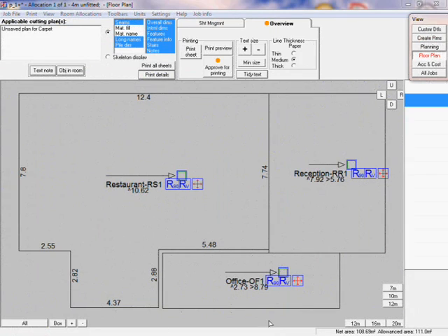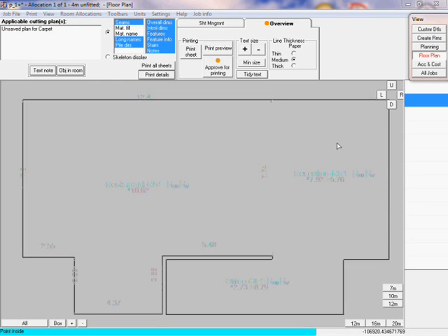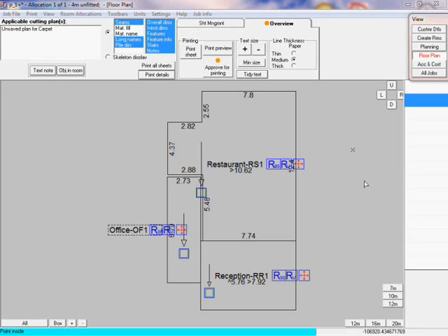We will now go to the floor plan and see here that it shows the architect's view of the property as represented by the outlines drawn. We can see the outlines we have drawn, which are located in their correct juxtaposition because they have all been drawn from the same PDF. And if we drag one room, then all rooms of the PDF set drag together. If we rotate a room, then all rooms rotate together. The controls of the floor plan are the same, whether the rooms have been drawn freehand or by trace around.